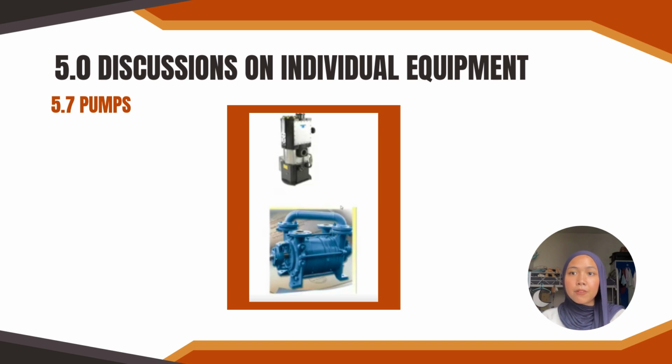Next is pump. Vacuum pumps are critical to ethylene oxide sterilization. They create a deep vacuum to remove all air before gas injection, ensuring full penetration. After sterilization, the pumps purge and aerate the chamber to remove ethylene oxide residue. Regular maintenance ensures reliable and safe operation.